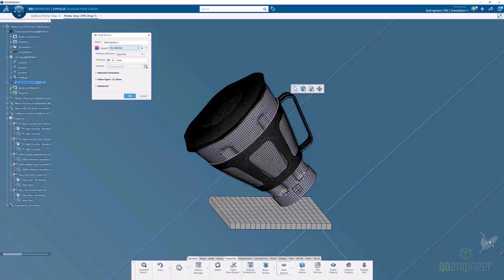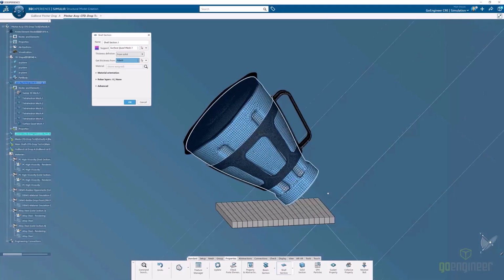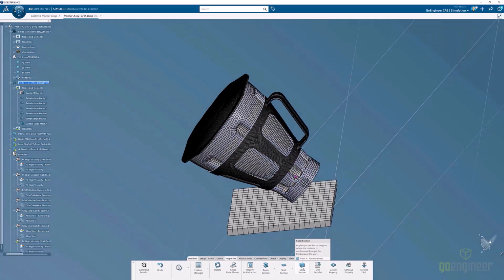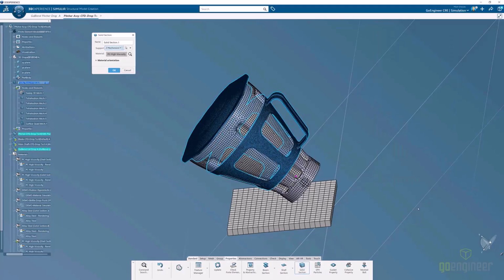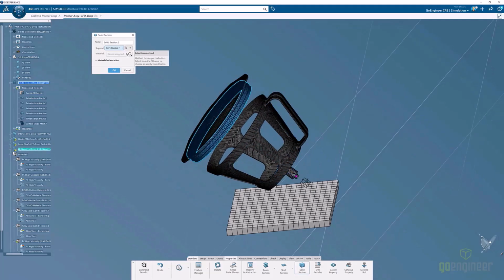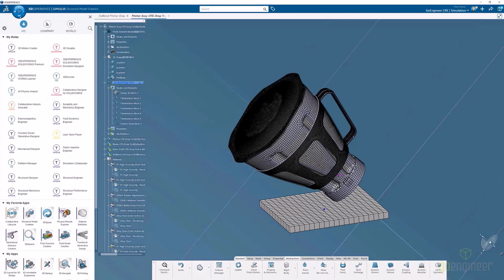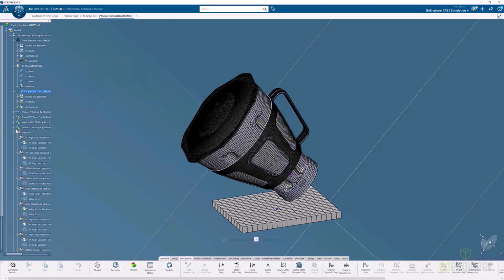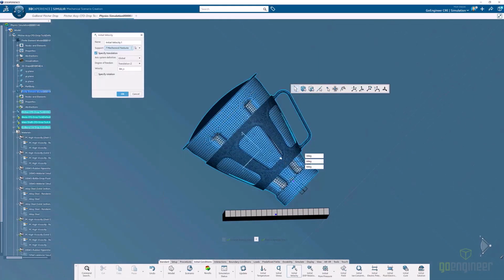We're going to go ahead and look at adding the materials into the model. So again, he's going to add these into the solid section, so the appropriate polycarbonate for the pitcher, the appropriate polycarbonate for the lid, the silicone for the gasket, and the nylon for the handle itself. So he's adding those all into the model. So we have those materials assigned. From there, we're going to go ahead and set up the boundary conditions. So inside of 3D Experience, what we can see is going to switch over to Structural Mechanics Engineer, and he's going to start adding in things like the initial velocity.